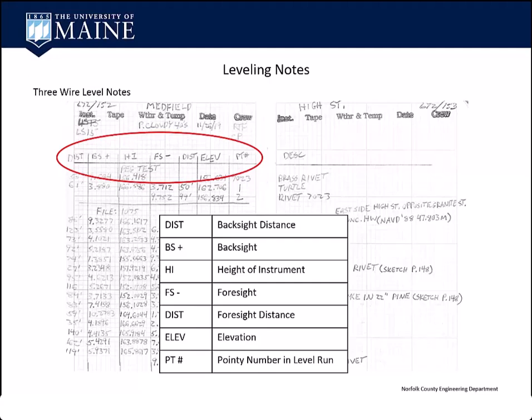You can see he's made a note there, NAVD 88. That's the datum we were working on, and the elevation was in meters. There was two things: NGS, a lot of DOTs, a lot of control work is done in meters, and then they convert it to international feet or US feet, depending upon NGS, whatever state it might be in that they've established the work.